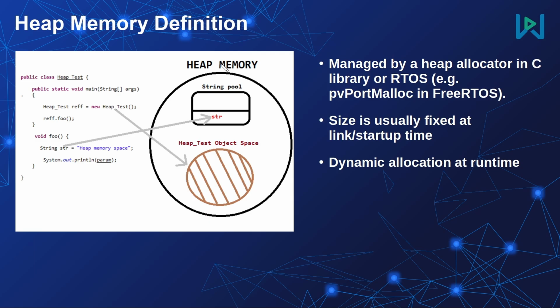On embedded systems, heap memory is just a memory segment that can be allocated as part of our RAM memory within the device. And this memory segment will be used across our embedded software to allocate buffers and save certain content and data within those buffers. And later on, we can free and deallocate those buffers from our heap memory segment.